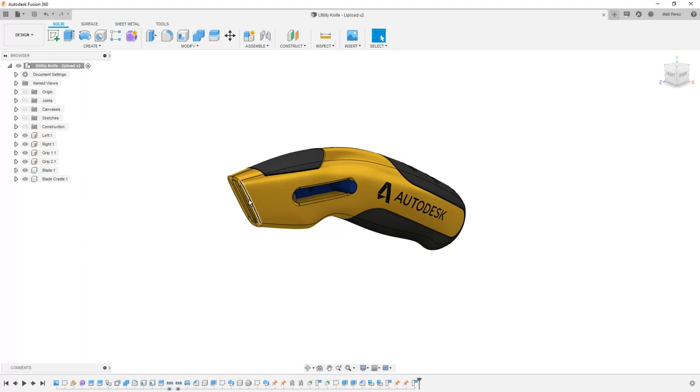But if we select something on design and right-click, you'll notice that menu changes. We now have Fillet and Chamfer, Show Hide, Select, Unselectable, and then we have Find in Browser and Find in Window. For example, if we select Find in Browser, it's going to expand that component in the browser, highlight the body where that edge is contained.